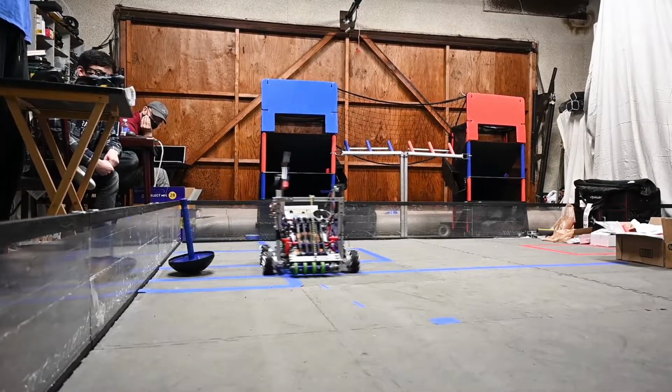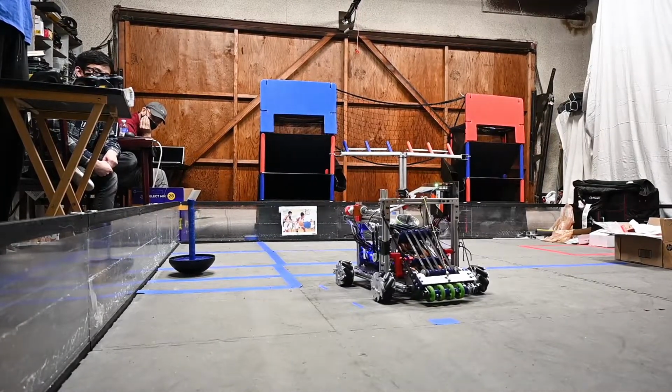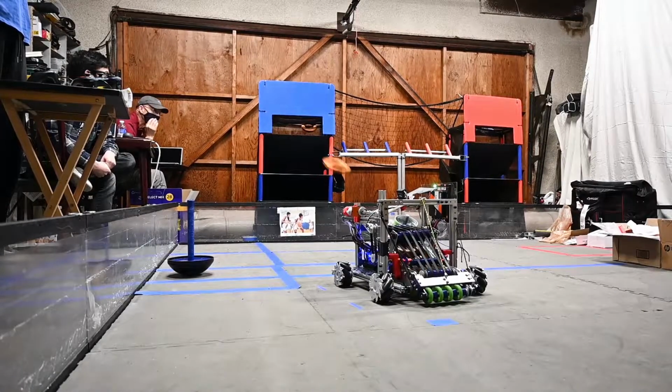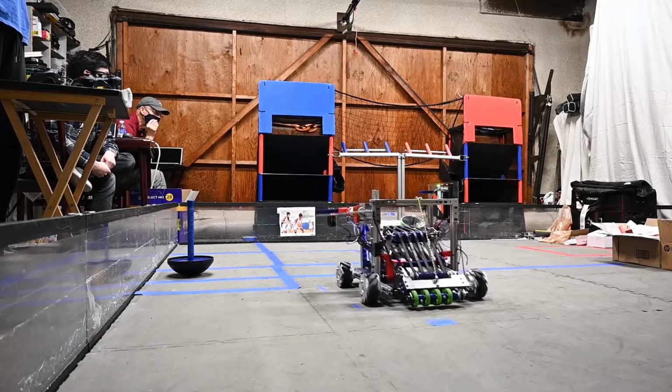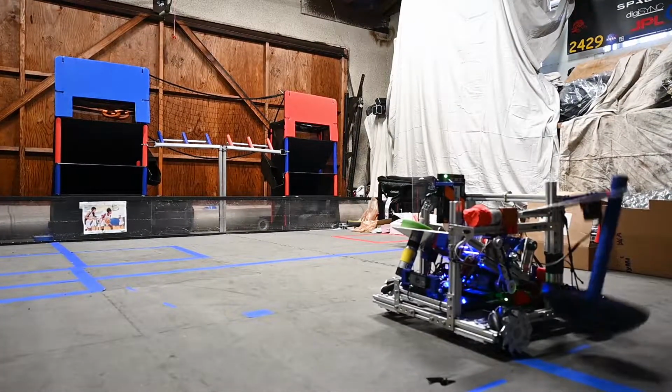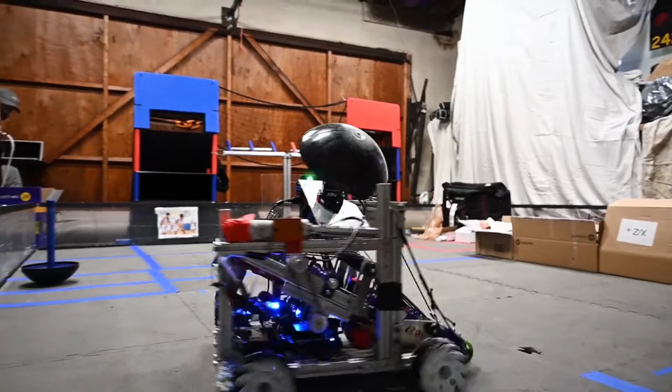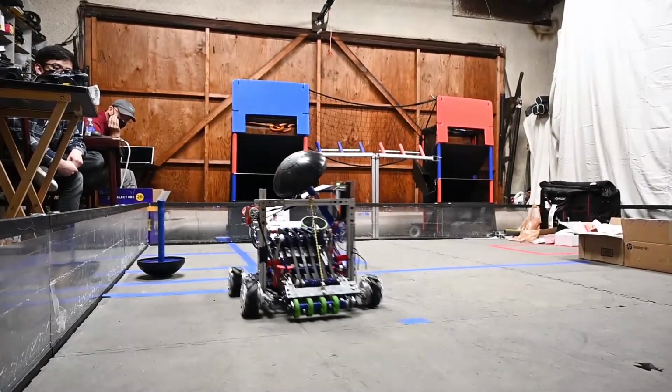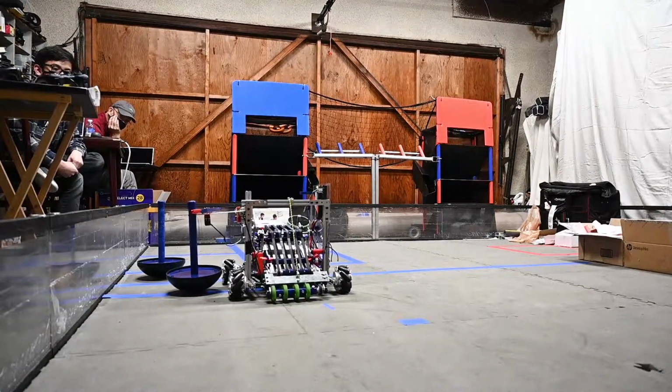When we notice a dip in the shooter's velocity, we stop our conveyor belt for 200 milliseconds to allow our shooter to get its speed back. In addition, our camera Vuforia allows us to track where the high goal is and when to shoot during auto, ensuring a perfect shot. PIDs are essential for Autonomous to make sure that we are on the right and straight path.